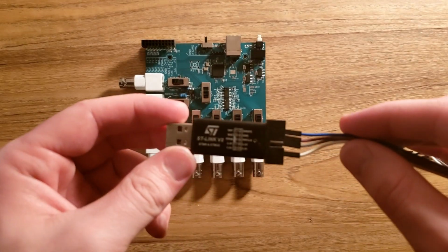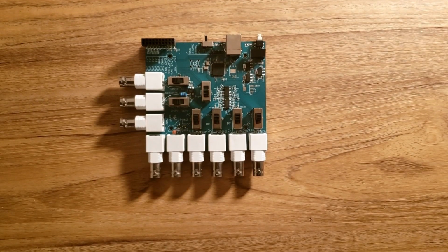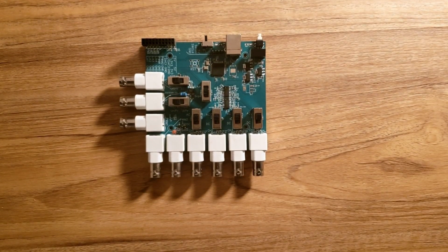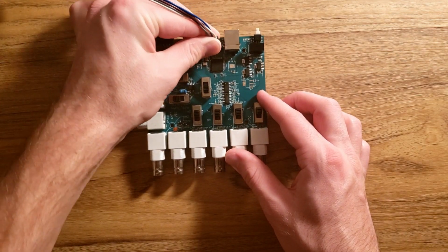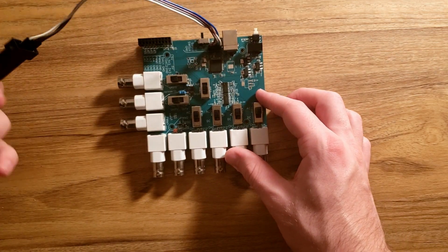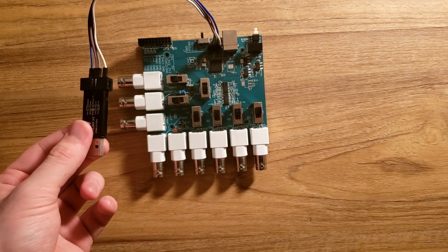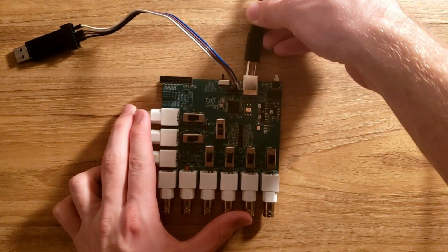I use an ST-Link with the STM32 Cube programmer. I also like to use the ST-Link utility tool, which I find to have more functionality and more control over sector erases and programming, as well as viewing the registers in memory. After we upload the firmware, we can test the board.